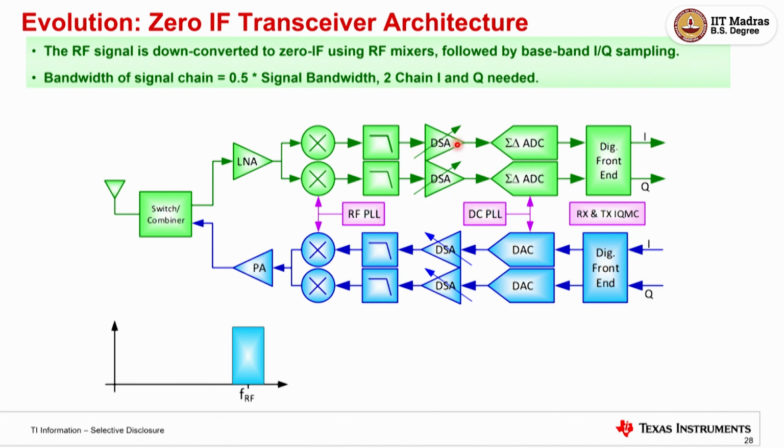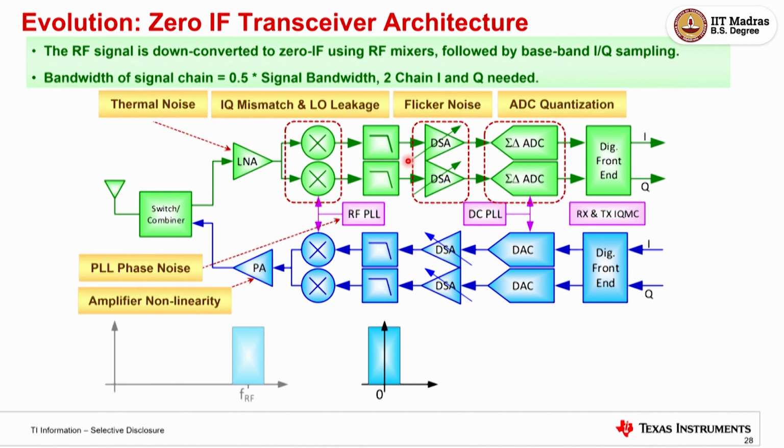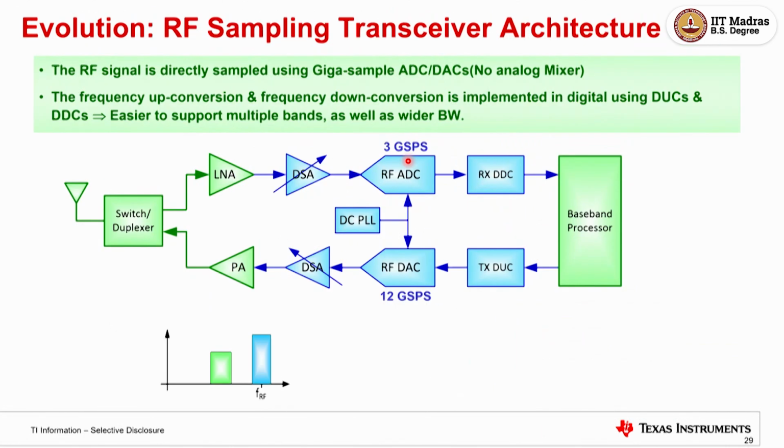You can build all this in semiconductor technology with very small size, but the filter size is decided by physics, so you can't do that. So the filter is removed, but you replicate it with two signal hardware chains, and how efficiently you can do it in area and power is the differentiation that you bring. You're removing the filter, making it smaller, but you're putting in more signal chains. That's where innovation comes in circuit design or whatever process technology you use, to double this chain. So that is zero-IF.